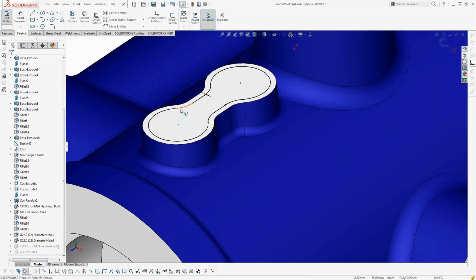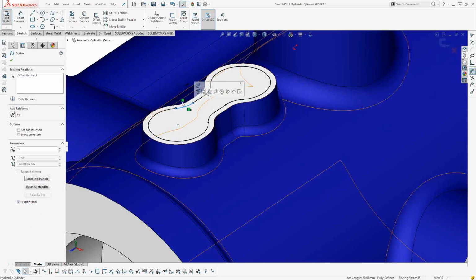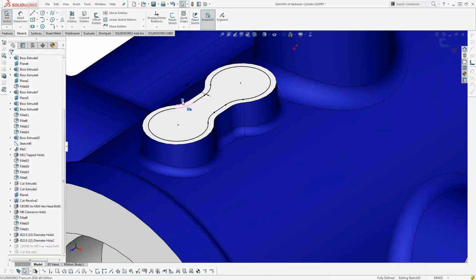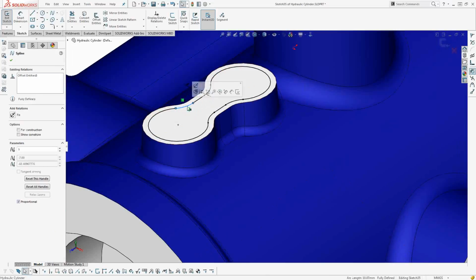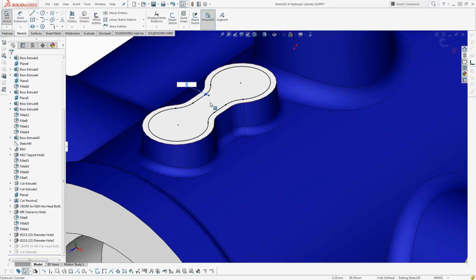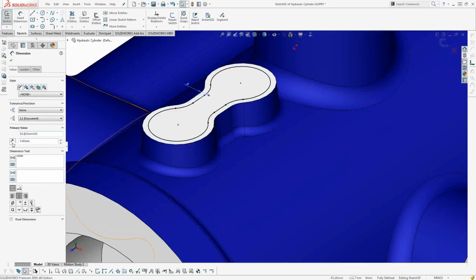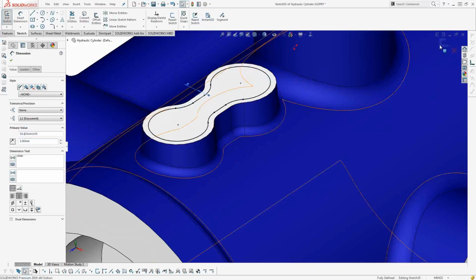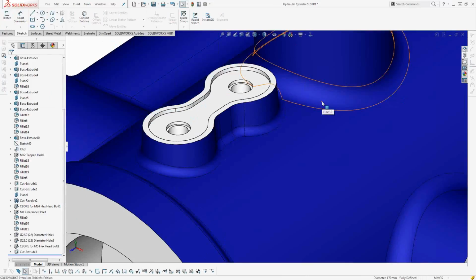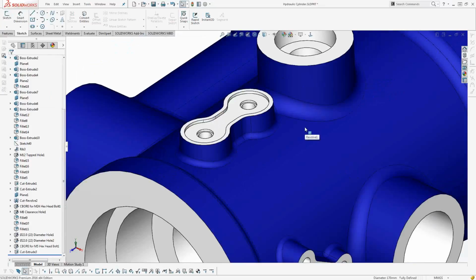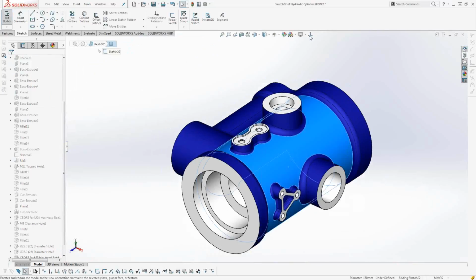Now, in the past, we've had the ability to create offset entities, but a limitation that we've had with the tool is that once you create the offset entity, there's no way to change it back. So I'm going to go ahead and highlight this offset entities relationship in my sketch here, and you'll notice that there is now the new ability to come in and reverse the direction of an offset dimension. Okay, so you can just toggle that back and forth to your heart's content, and it goes right into place. Very cool. If we were taking a closer look at this sketch as you saw before,